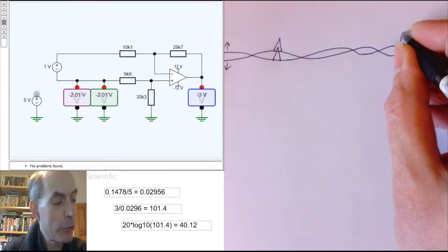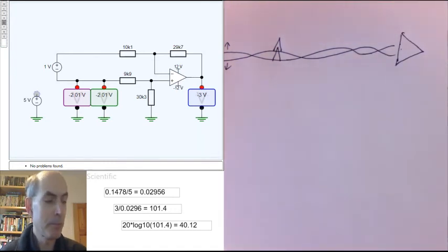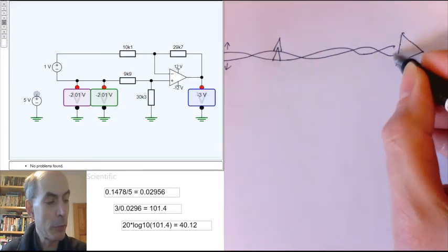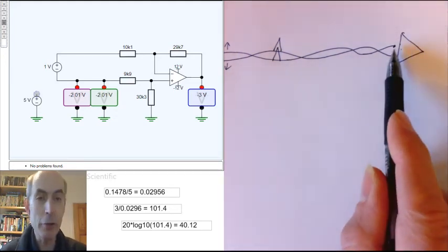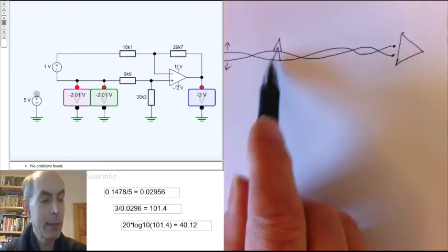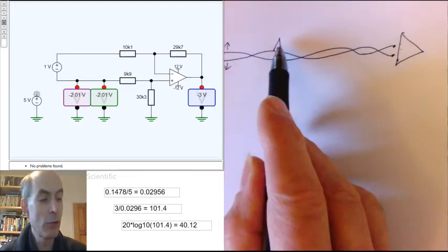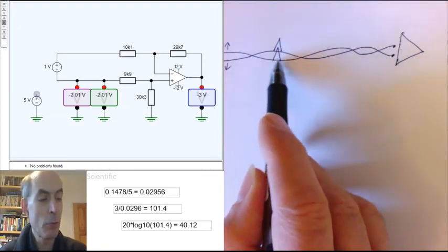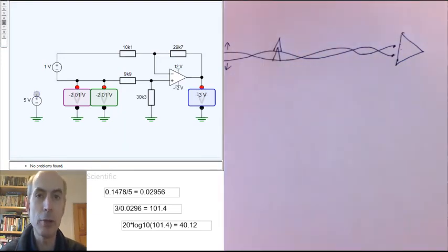If at the receiving end, at your mixer, you have a differential amplifier, which amplifies up the difference between these 2 signals, then it should recover the very small microphone signal and get rid of this noise spike because the noise is equally placed on both of these 2 signals, and if you subtract them, the noise should cancel out.